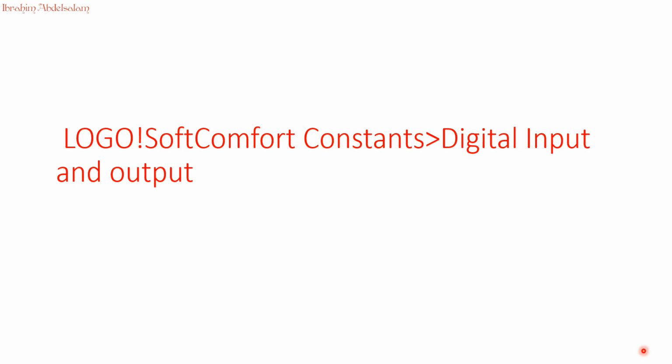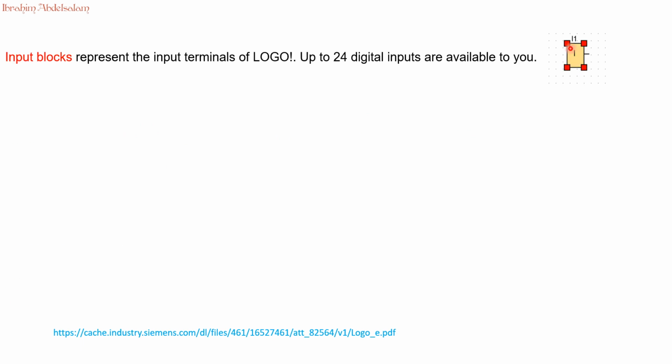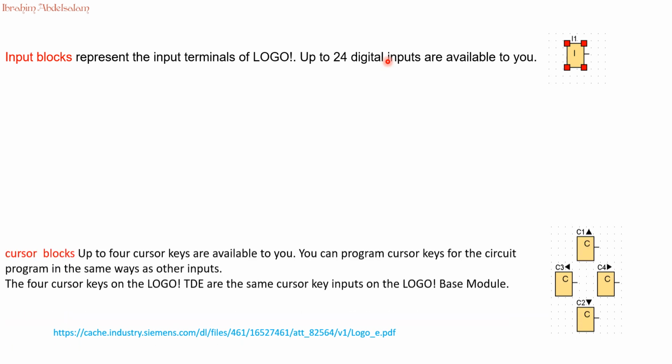In this video, we'll talk about digital inputs and outputs in LOGO! Soft Comfort. The input block looks like that, starting with I followed by a number, up to 24 digital inputs, since the LOGO maximum digital input is 24.